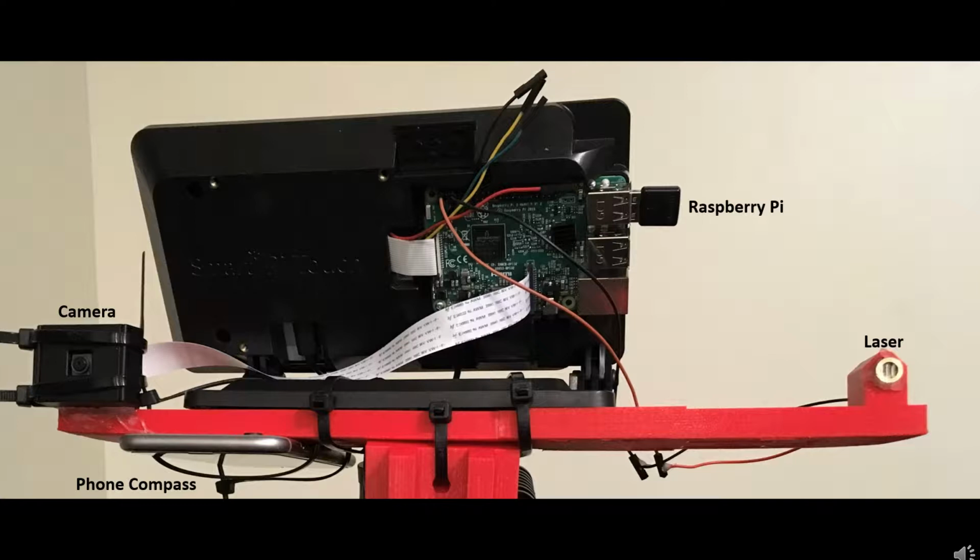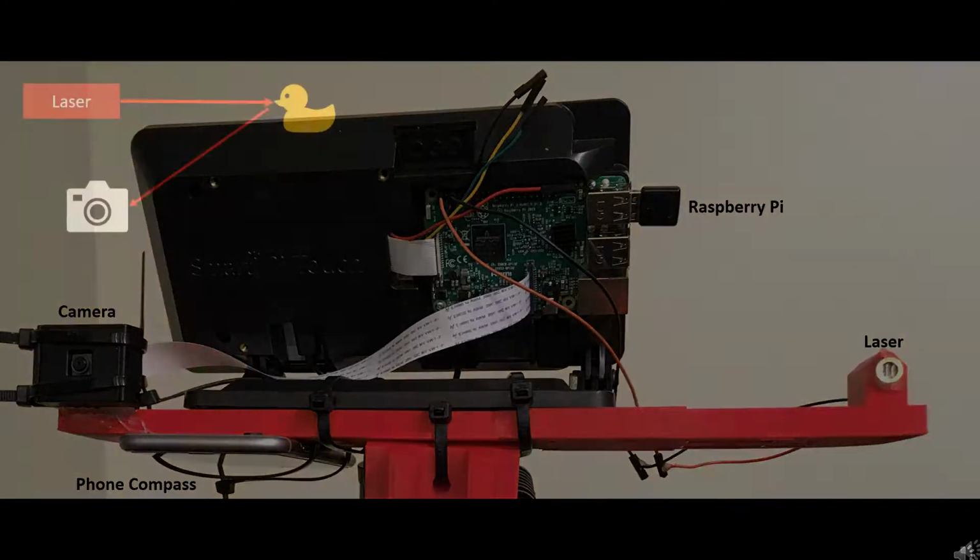The receiver, a Raspberry Pi camera, is originally mounted 12 inches away and positioned in parallel with the line laser. The distance to the object will be calculated using a triangulation method. For this method to work, the laser emits photons which reflect off the target. The camera receiver will detect those photons.